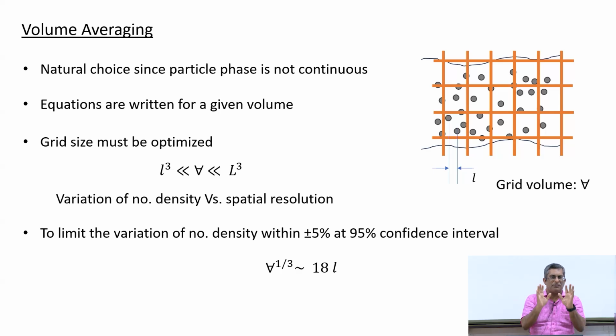It is like, let's say, the definition of fluid density. Let's say you have a single phase flow, as we had discussed earlier. So what is density? Let's say we are considering a gas: mass of gas per unit volume. Now if you choose your volume to be very small, which scales with the mean free path of the molecules, then obviously you will have fluctuations of density. Density means the mass of a number of molecules divided by the volume.